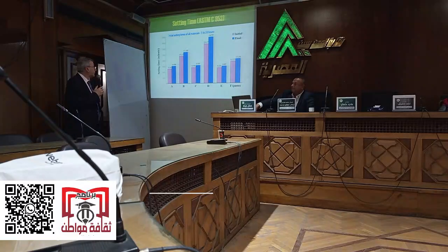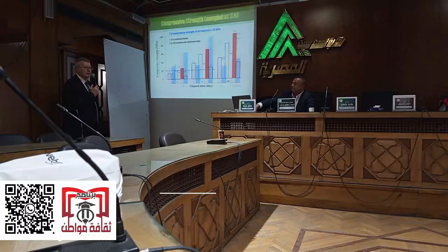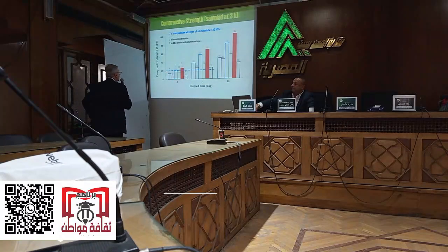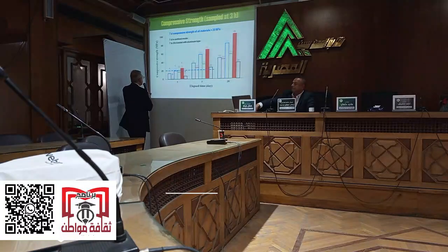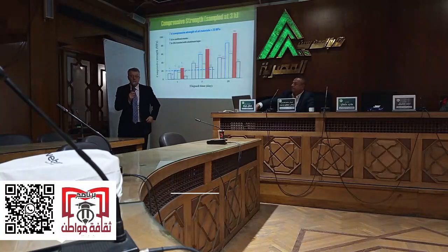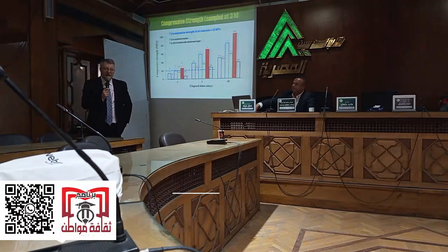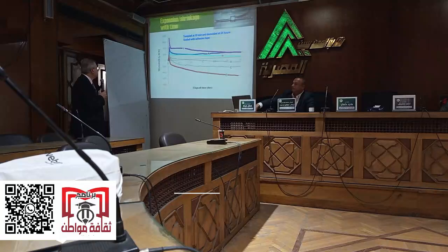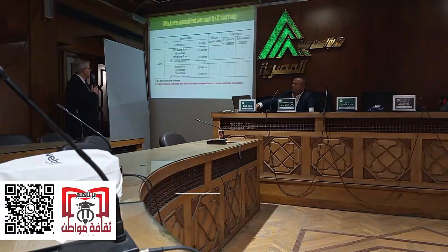I'm almost done. Setting time, initial setting, final setting. Again, 8 hours initial, final setting anywhere between 9 hours and 24 hours. Compressive strengths, we wanted to have compressive strengths of 20 megapascal at 28 days, and you can see everything is okay. There's no red flag at all. Next, shrinkage.